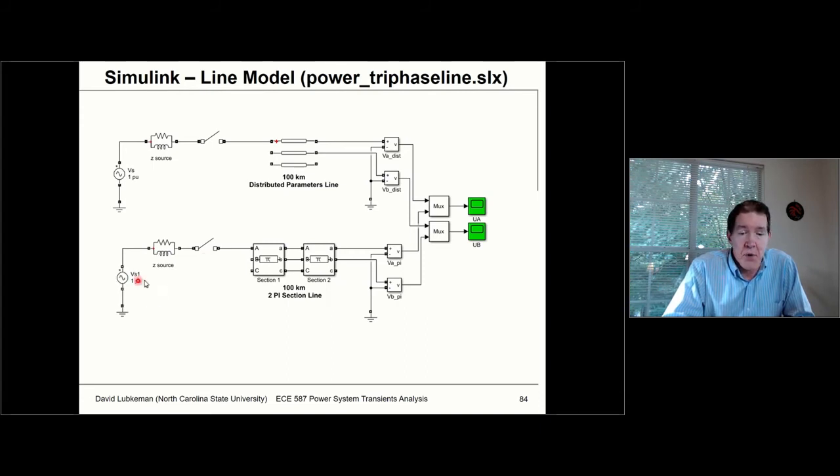So note you have a source impedance in this case. What's interesting is when you're doing transients at higher speeds, instead of using an RX in series model, you typically use an RX in parallel model, because you want to represent the surge impedance seen by traveling waves going toward the source.